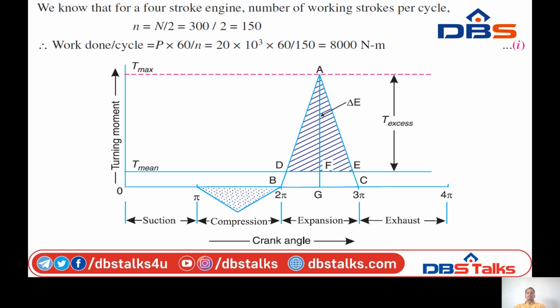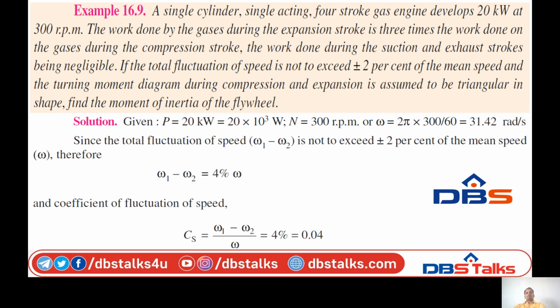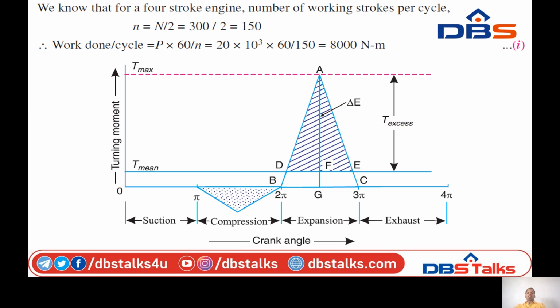It is only during the compression and expansion stroke, since in the question itself it is given that the suction and exhaust strokes are negligible. During compression and expansion strokes it is assumed to be triangular. So no need to draw a diagram during the suction and exhaust.